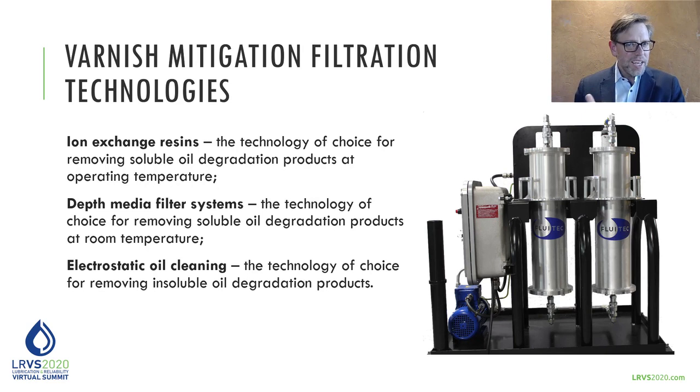In some cases, it may take some additive components out. In other cases, the viscosity may be too high for the technology to deal with. But in all cases, the cost to treat, say, a small hydraulic system, a couple hundred liters or a drum of hydraulic fluid, would be very, very high if you wanted to have a dedicated filtration system on. And so for many hydraulic systems, we need a little bit more scalable solution.